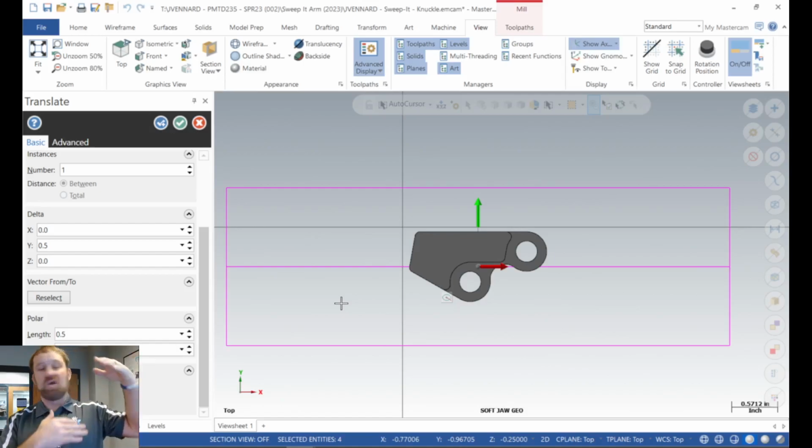But I need to put a little space in there and clamp on something to hold that space, so I can cut the pocket that's the shape of my part for my part to sit down in and hold on to it. The easiest thing you've got out there is your parallels. The parallels are an 1/8 inch thick, which is a small amount, but it's enough.